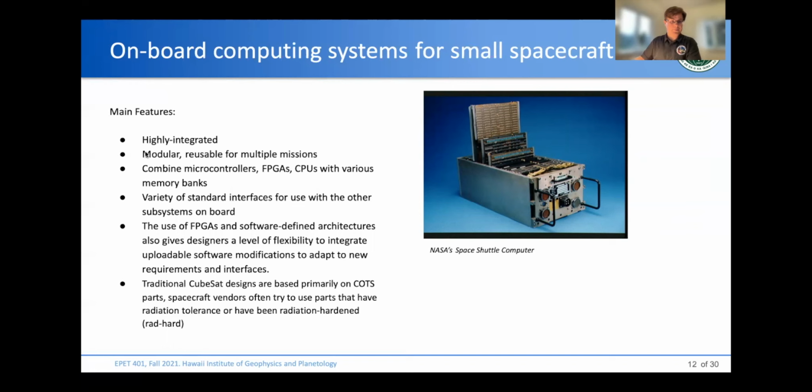And more recently, field programmable gate arrays, or FPGAs, have become quite common in flight computers because they allow us to actually program the logic or the hardware logic into that FPGA, meaning that you can implement different transistor circuitry, different electrical interfaces, even implement different hardware CPU implementations. So that is very important, becoming more and more important today.